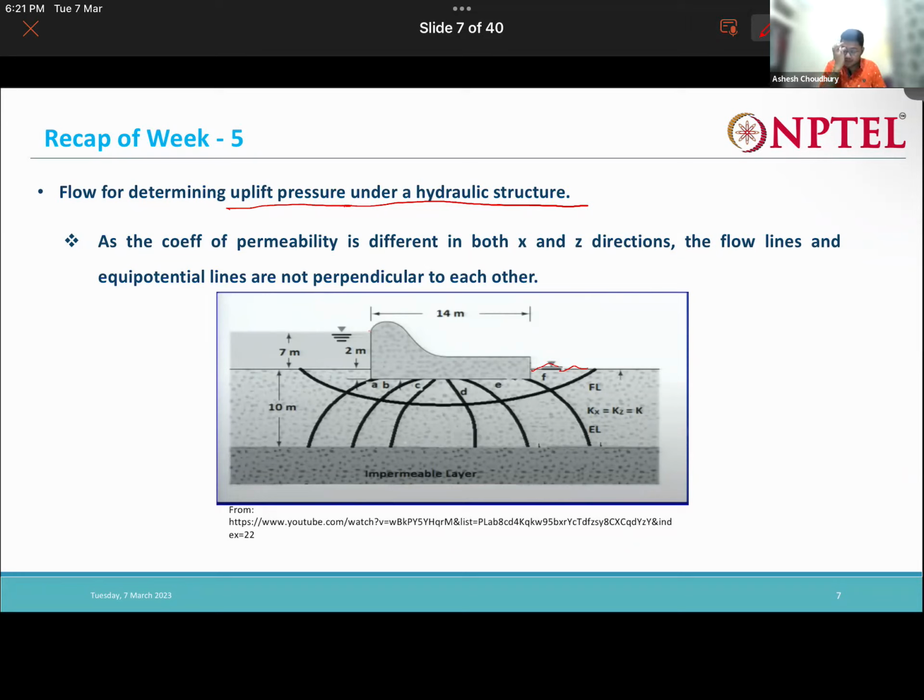From the heave, sometimes the soil starts getting eroded from this tail part. Due to this erosion, a channel is formed, which gives easy passage to water. So the main purpose of constructing the dam or hydraulic structure, which is to prevent the flow of water, is left unfulfilled.